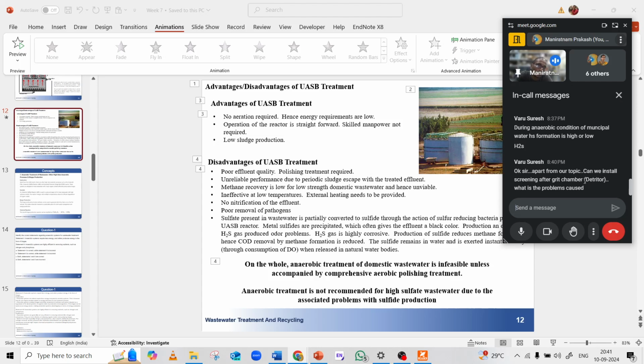Now imagine that in the grit chamber you are providing water which contains grit particles and also some larger particles, with size larger than grit particles. Then it will just increase the load of the grit chamber, and with time it will require high maintenance and will not be an economical option. So first we have to remove the larger particles. Once the larger particles are removed, then we remove the smaller particles. And once the smaller particles are removed, then we go to the removal of suspended particles.